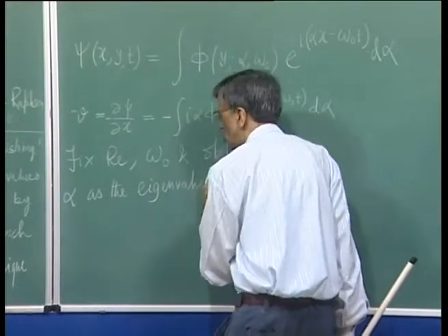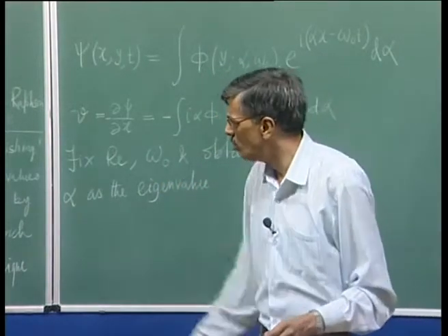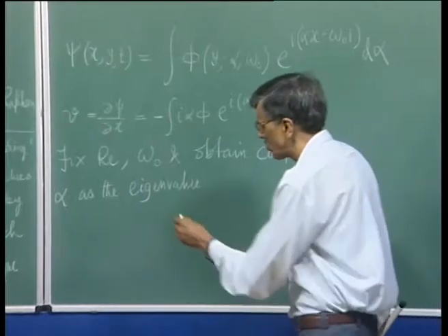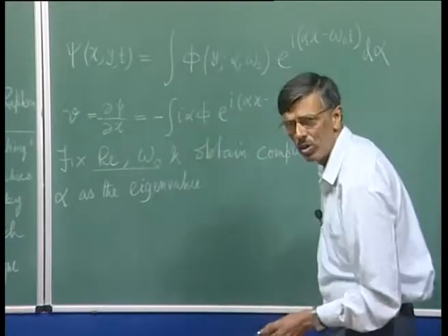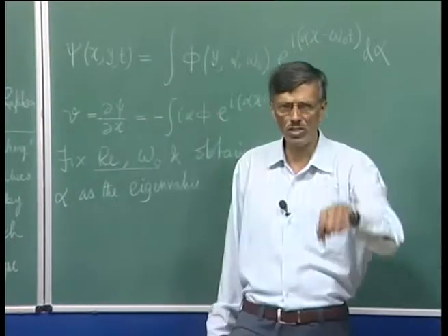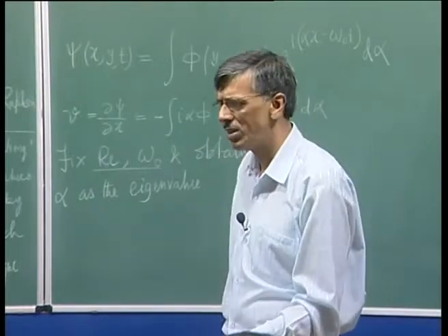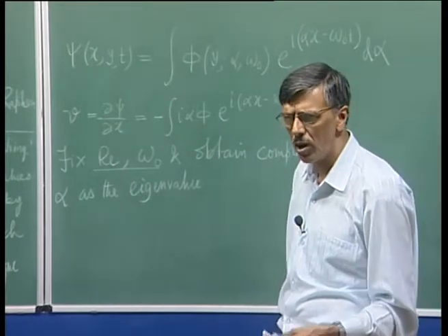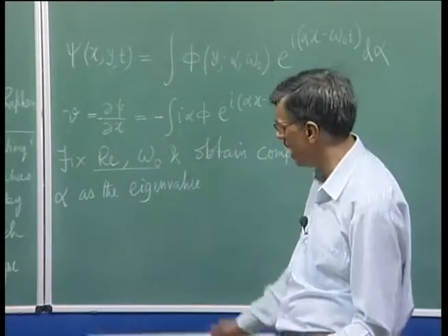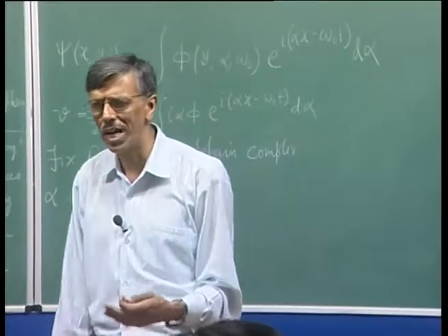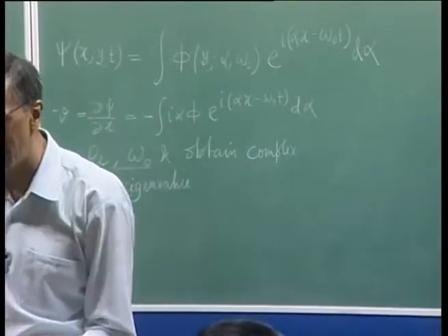We go through the exercise that we talked about. These two, Re and omega naught, are fixed. We start off with some kind of initial guess of alpha, march down up to the wall, and investigate the status. If it is not 0, then it is not an eigenvalue. That gives you an initial guess for the eigenvalues.